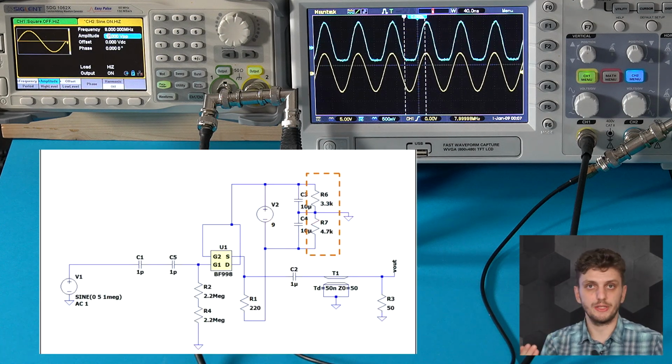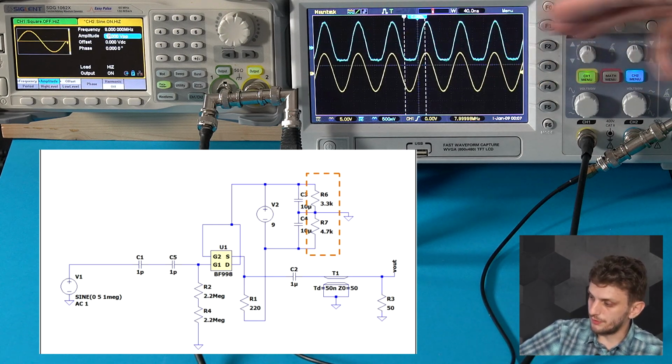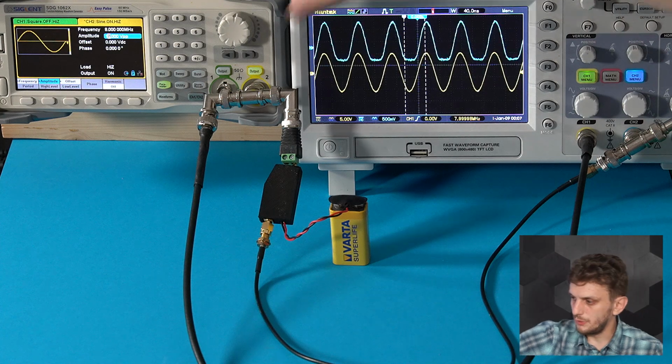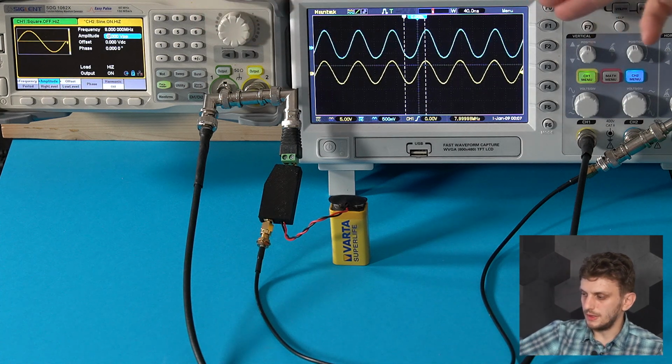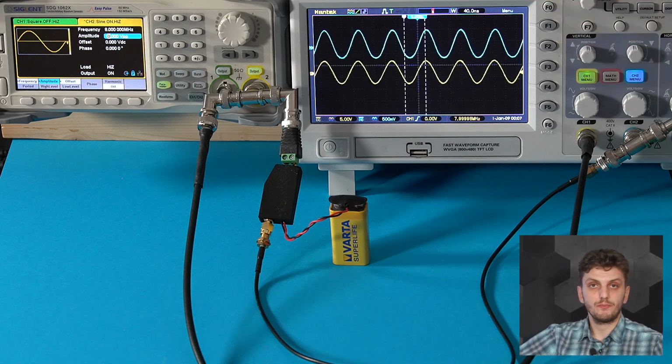Now this of course can be improved by adjusting the voltage divider from which the reference voltage is set. So right now I have a 3.3 kilo ohm and a 4.7 kilo ohm resistor, but we could maybe put in a potentiometer or something to fine-tune this value so that the signal is perfectly centered. But anyway, regardless, we should be able to measure quite easily and quite well a plus minus 5 volt signal. So for that at least the probe should be good enough as it is.